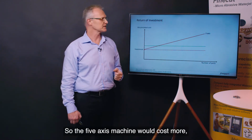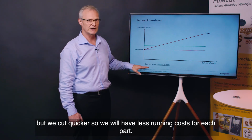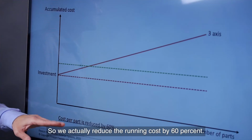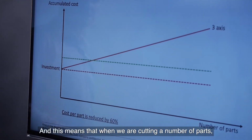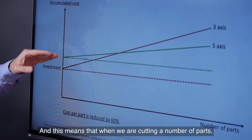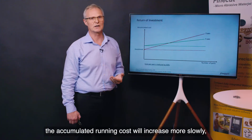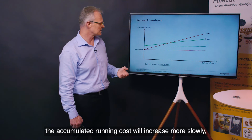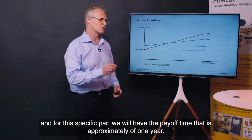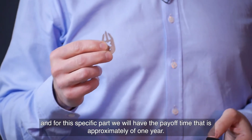So the 5-axis machine would cost more, but we cut quicker, so we will have less running cost for each part, so we actually reduce the running cost by 60%. And this means that when we are cutting a number of parts, the accumulated running cost will increase more slowly, and for this specific part, we will have a payoff time of approximately 1 year.